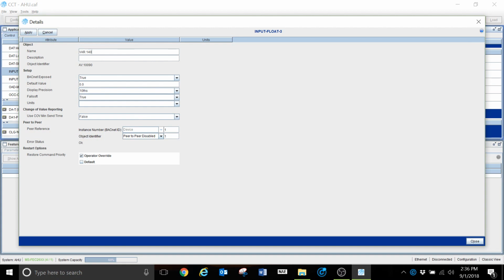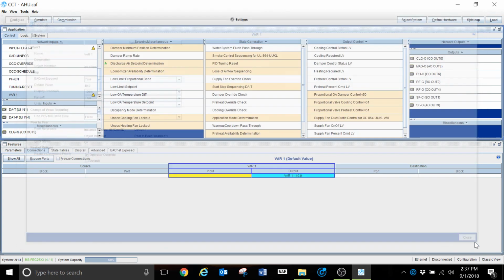The reason is one of the buildings that we have; this is one of the variable values for that particular building. Once I enter that, I'm going to hit OK. What that 40 value means is that when the input on our outside air temperature to that span block is 40 degrees or below, that's when that output is going to be at its maximum.